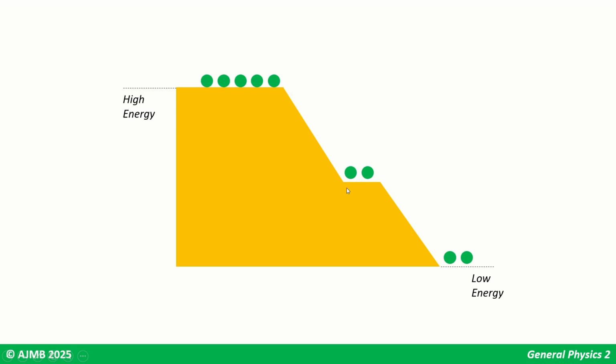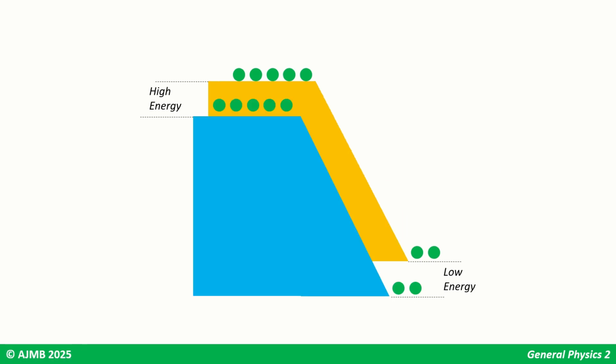There would be a decrease by 30 volts as it passes through the first resistor, and then how much is remaining? 30 volts, right? So after it passed through the second resistor on its way back to the negative terminal, the remaining 30 volts would be spent as well. So when it reached the negative terminal, that's 0 volts. Okay, so this is the voltage drop that happens when my resistors are connected in series.